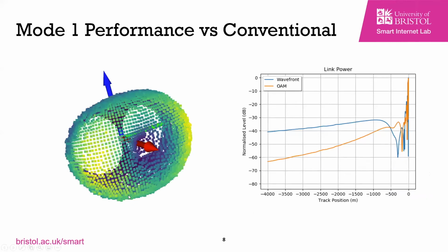Now, this is that same mode in terms of amplitude in the far field, and you can also see the problem with OAM modes when you're attempting to use them for communications in free space: there is this null on boresight, and as you go up to higher order modes, the null gets deeper, and the donut of maxima actually spreads out further and further. So as you stack on these higher order modes, you get less and less received power at your receiver.